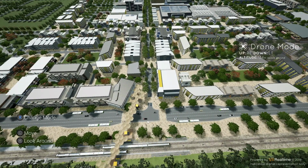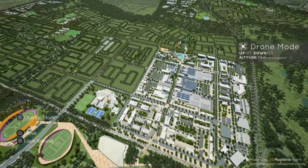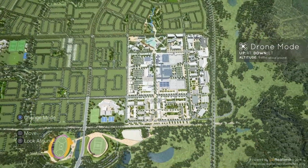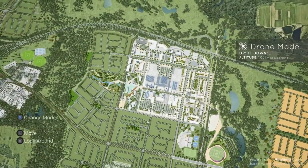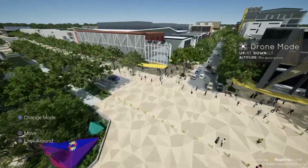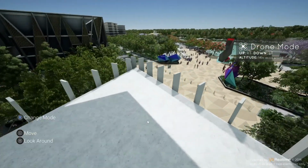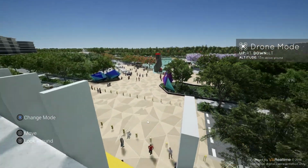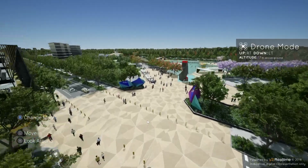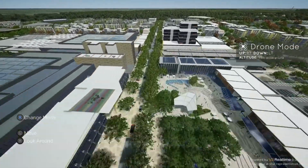Now just a little trick here, there's another button on the gaming controller above the right trigger. If you hold that and do any action, you will actually fly faster, so that will allow you to use your drone and fly a bit faster than the relatively slow default speed. So the drone is quite good to fly around at a semi-elevated level, or even say with this rooftop cafe here, albeit crude, you have the ability to go down and look at view lines from these particular angles. That would be a little bit harder to reach if you were just in walking mode or aerial mode.